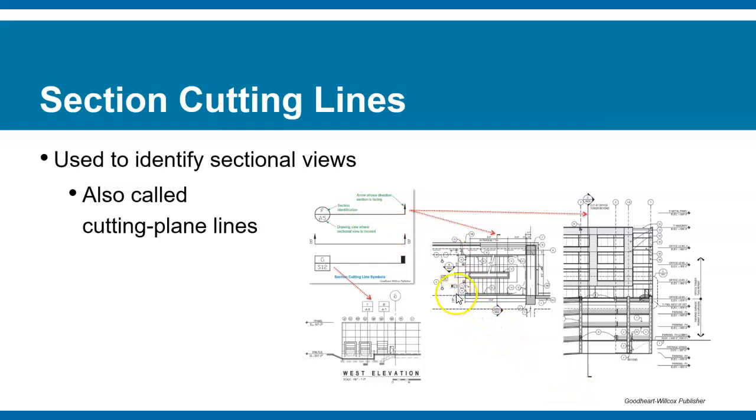And you see what we're looking at in this plan view. It looks like I see some walls, I see some columns, I definitely see some center lines, some hidden lines there. I also see some big fat section, solid lines, which looks like a stairwell. This looks like walking up a set of stairs, going to a landing, and then coming back and continuing to go up.